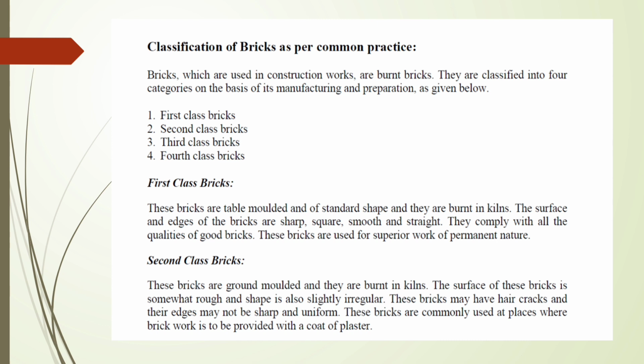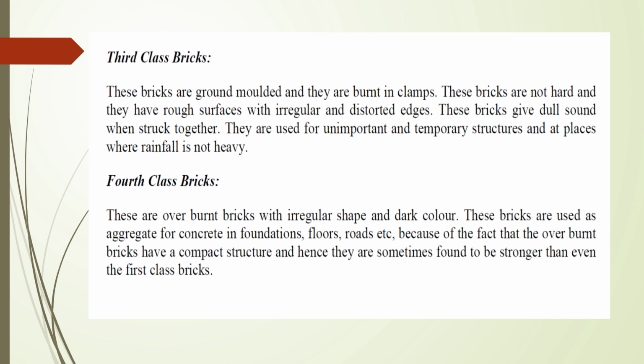Second class bricks. The bricks are ground molded and they are burnt in kiln. These bricks are commonly used at places where brickwork is to be provided with a coat of plaster. Third class bricks. These bricks are ground molded and they are burnt in clamps.